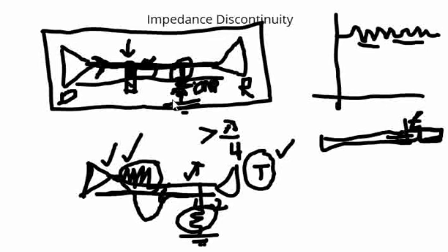And if you are using a resistor, ensure that this resistor is placed as close as possible to the transmission line with the shortest stub. In case the stub cannot be eliminated, if the resistor has to be DNP, the stub will be as small as possible, which is helpful to eliminate any discontinuities. And as we talked here, use proper terminations, by using simulations such that we have a very good termination happening without any discontinuities.